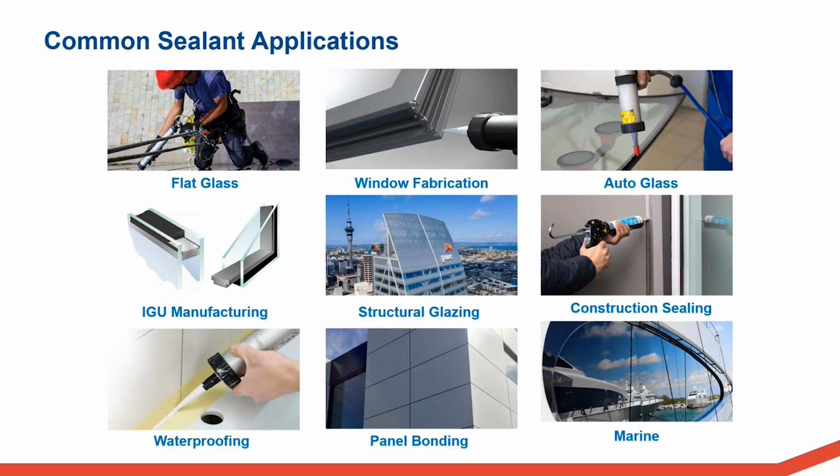On the other hand, for an air seal or an expansion seal, you might need to design for high thermal or seismic movements, in which case you may select a sealant with significant movement capability. Certain applications may call for a specific sealant type, which must be used. Other applications may allow you to consider several different sealant options to determine what product works best for you.